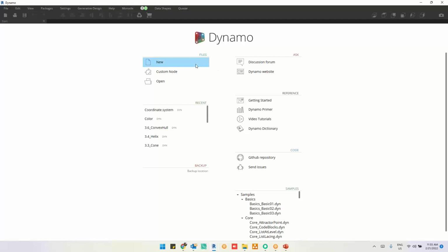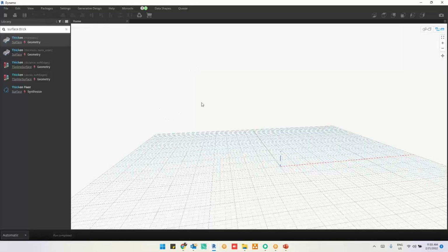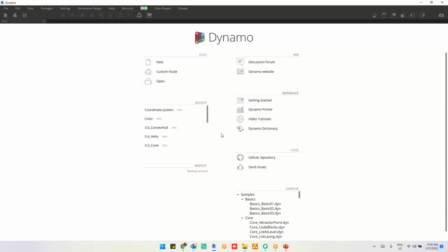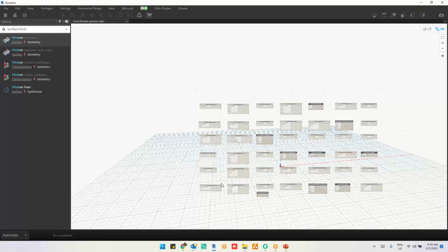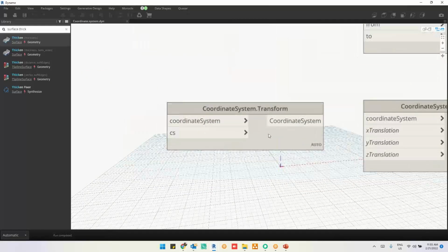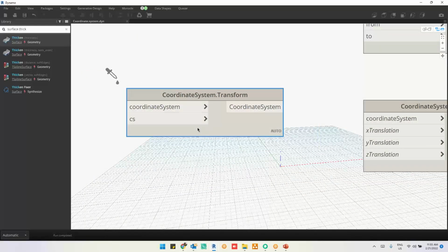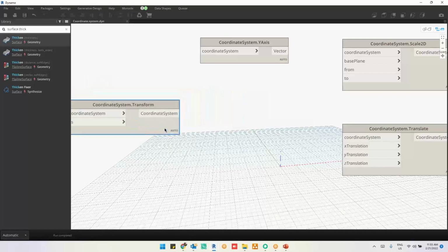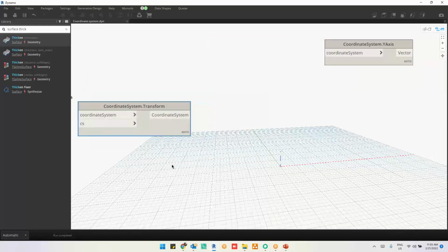For example, you will be connecting those coordinates. Let me show you that. Yes, in projects, all our projects are on shared coordinates only. But when you use this Dynamo script and you want to place families on the shared coordinates, you will have to use one node to transform this origin to the shared one. So this is a coordinate system and this is a coordinate system. You have to use this coordinate system always. For example, this is the finalized one.